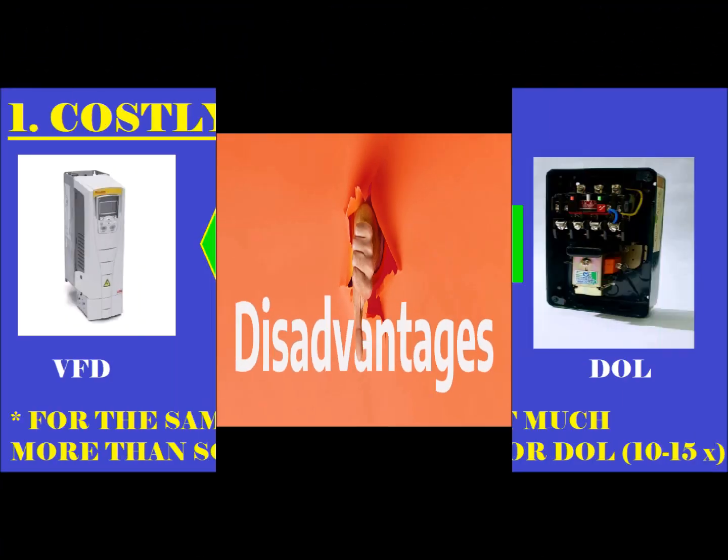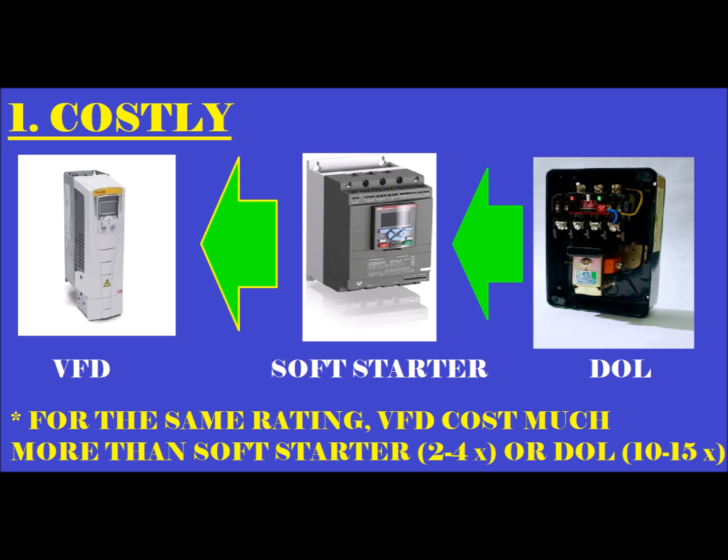Next we'll come to the disadvantages. The first point we'll take is the cost. Drives are very costly as compared to any other starter in that range, that can be a soft starter or a DOL. For the same rating, a VFD will cost 2 to 4 times more than a soft starter and almost 10 times more than a DOL. So that's how costly drives are.